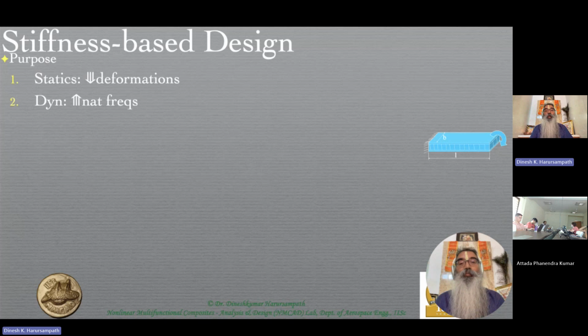Some of you might be aware how helicopters fly in terms of the overall qualitative controls that the pilot has. Of course, he has the rudder pedals, which make the helicopter yaw. I forgot to bring a helicopter model over here, so I've just demonstrated the Beluga. Essentially, when the stick is pushed left or right, you have a roll, and if the pedal is moved, you have the yaw, and if the pitch stick is moved front or back, then you have the pitch. So this is as far as a fixed wing aircraft is concerned.